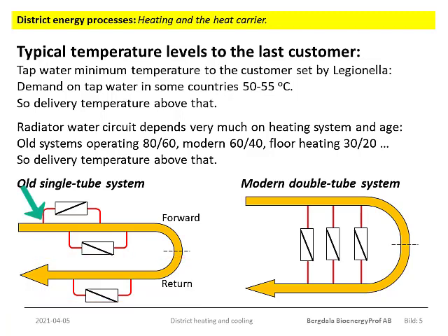So the customers extracted the hot water to their heat exchangers from the main pipe, and after the water had passed through the heat exchanger, it was returned to the same pipe again. If the customers are connected this way, you will realize that the volume flow of water in the main pipe more or less remains constant along it, but the temperature in the main supply pipe will drop. So the last customer would get water that was of a low temperature.